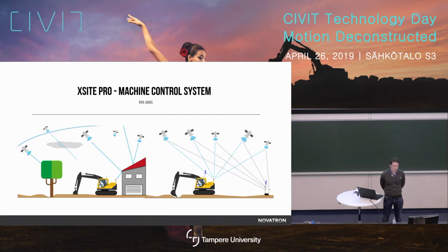If you actually want to get within centimeter accuracy, then we need to use RTK GNSS, which basically means that we have a correction signal telling us what kind of disturbances are affecting this GPS. So there can be, for example, atmospheric disturbances. Sometimes there are some obstacles actually on the way, stuff like that. But what RTK GNSS can fix are mostly the atmospheric disturbances.